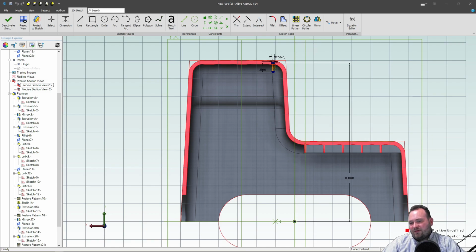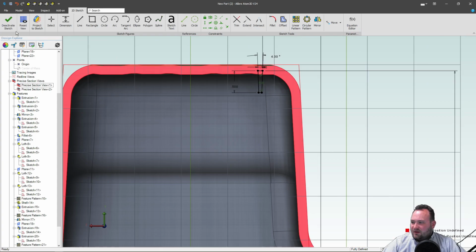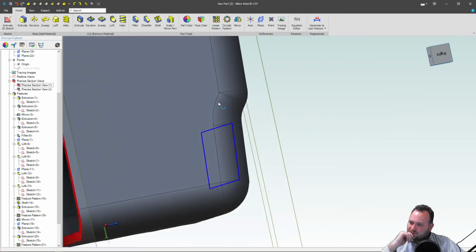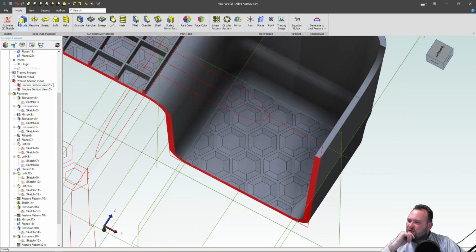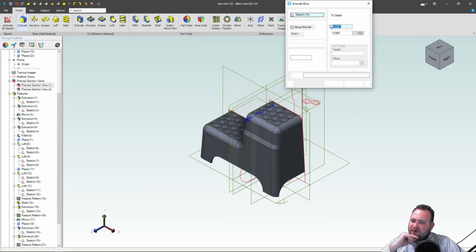Let's say 1.25. We'll deactivate that. And again, you can make the ribs a bit longer if you want, because we are having our sketch be partially inside due to the uneven surface. Let's do an extrude, and we're going to the right side. So what we have to do, after thinking about the graphics, is establish our design intent to go up to next.